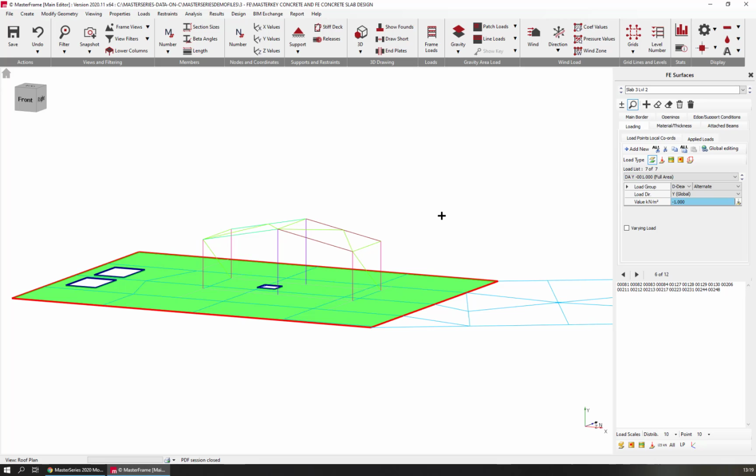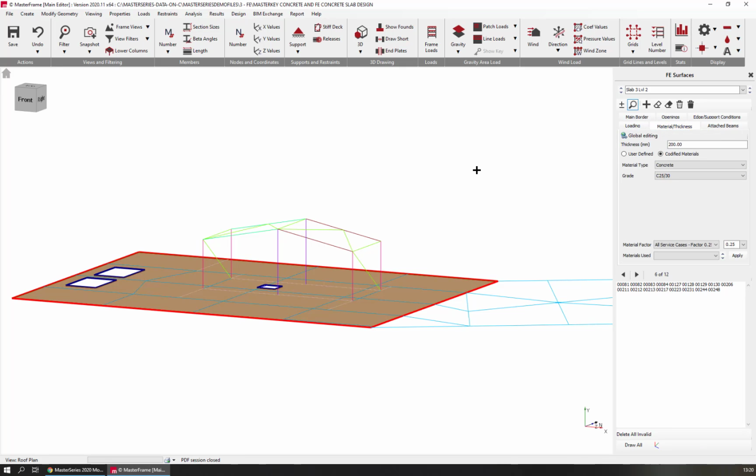The openings again are very straightforward. The one thing we haven't talked about here is very interesting, is that when we're looking at our slabs, when we're dealing with our deflection loading cases, then we want to take a weaker material to allow for creep and to allow for cracking.